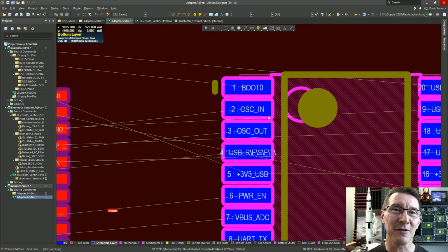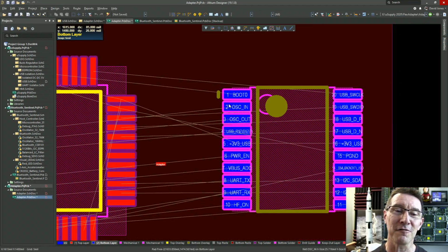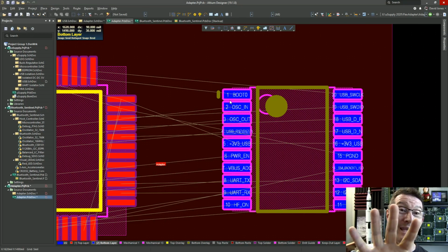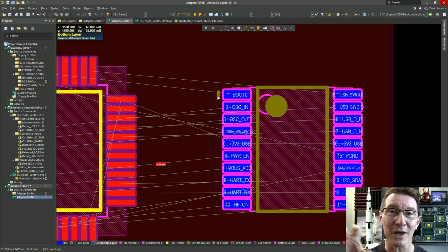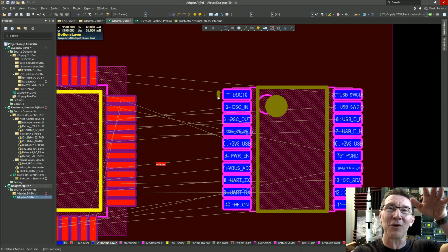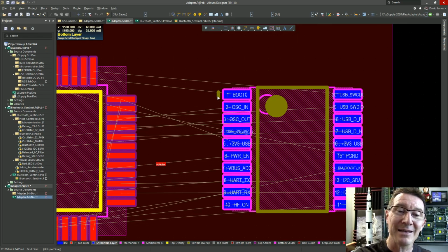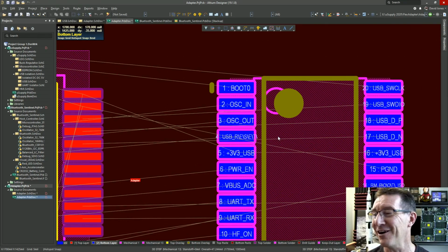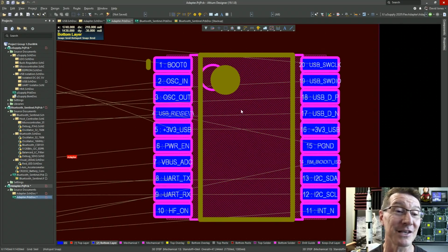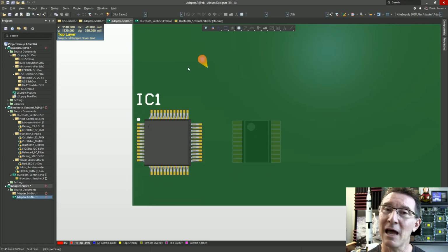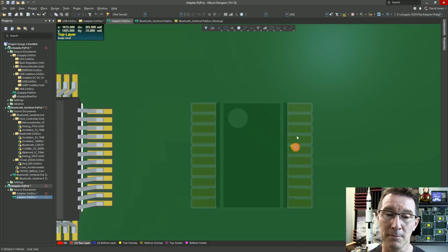So this one's actually been flipped twice. Not only is the component flipped from the top side, the red side, over to the blue side, but then it's been mirror imaged like that, because we have to connect down to another board underneath which has this particular pin configuration. If you didn't realize that, you could completely come a gutser and get your footprint back to front. Anyway, we're just going to have a chippy on there. Haven't defined the board outline yet, but yes, we're going to have a pad. This won't be a chip, this will just be some vias.